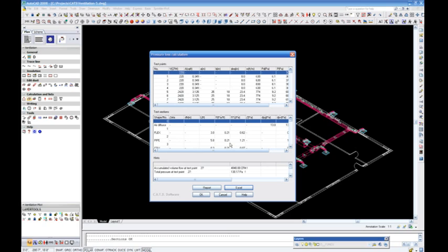The pressure drop of the supply air system is 130 Pascal, or 0.5 inches static pressure. The total external static pressure of the system is 230 Pascal, or 0.83 inches static pressure.